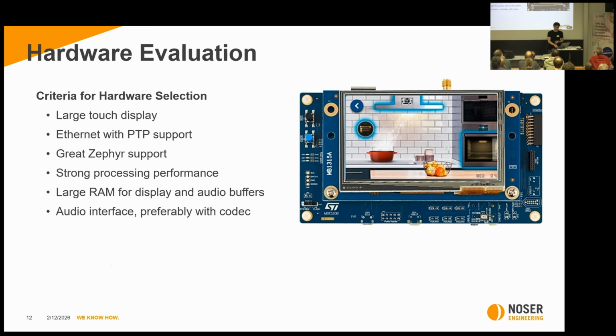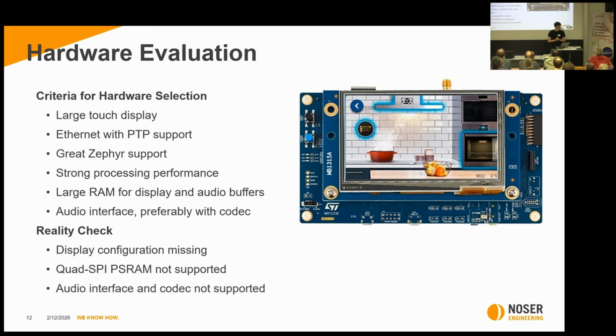Well, quick reality check. It's an amazing display, and Zephyr offers amazing driver support regarding graphic displays, the LVGL library. It's amazing. The only thing missing was the little configuration file for my display, and it was a rough start to get the device tree working, but I eventually did.